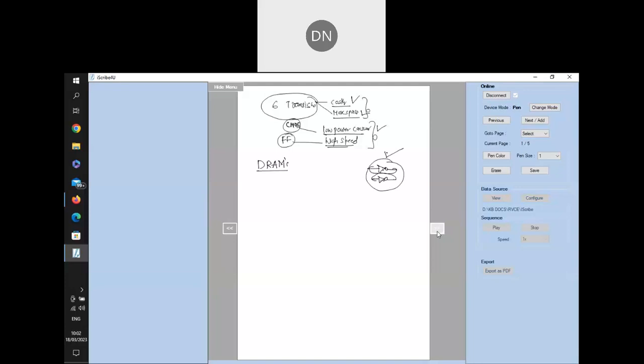How is it possible? Yes, there is a component in electronics, known for centuries, which can store the charge present in it. That is called a capacitor. The whole concept of DRAMs is this: the capacitor is a fundamental element used to hold the voltage or charge present in it. This facility of holding a certain voltage, 1 or 0, is the fundamental principle behind DRAM. But when do you charge it? When do you release it?